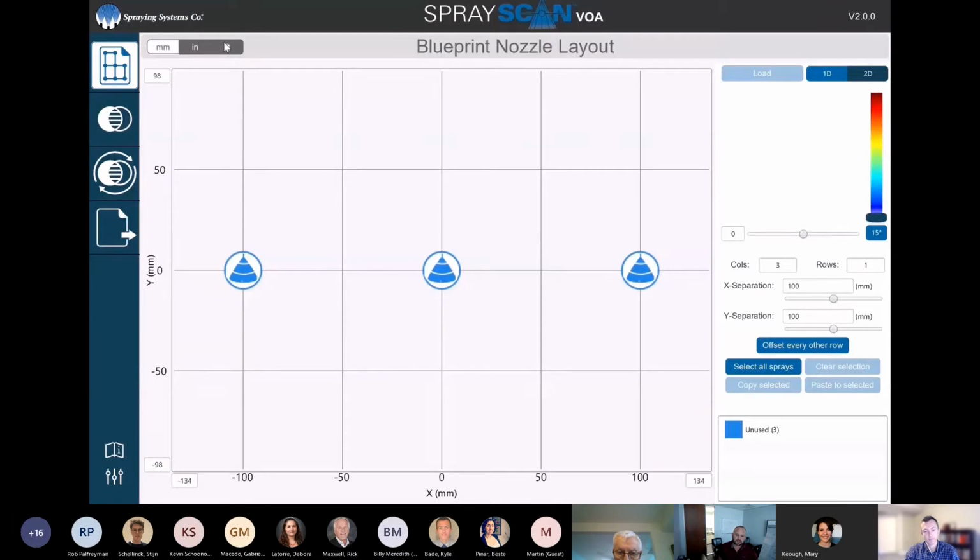Yeah, and Kyle too, what's I think important, not only the geometric, right, the theoretical spray coverage, we can get a little bit more granularity on that too, and also be able to see what impact gravity has on how that spray pattern is being formed and contracts or expands, and that could change based off of your pressure drop versus what's sprayed at the lab.